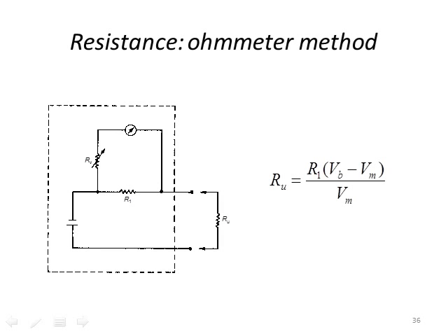Resistor ohmmeter. In this configuration, you can see that we apply a potential. We have variable resistor RV and R1, and we connect a resistor RU that we want to determine across the output, and then we get RU is equal to R1 times the difference of VB and VM over VM.